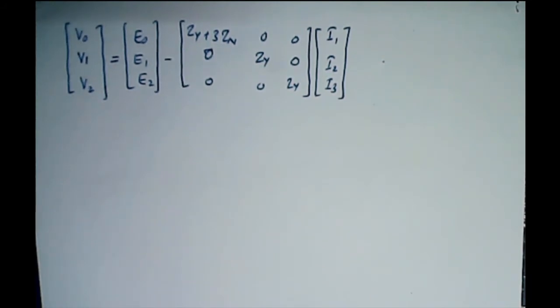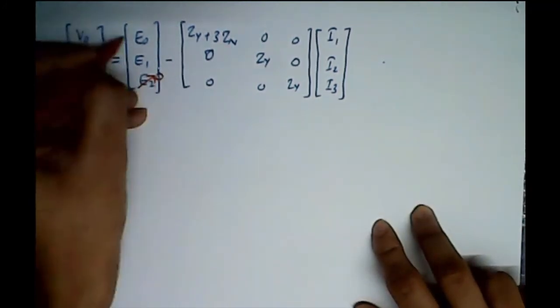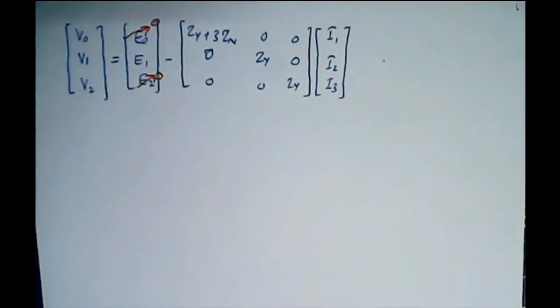This means if the magnitude of a generator rated at 11 kV gets low, then all the phases will have a magnitude of 7 or 8 kV. Now this means that the internally generated voltage in a generator is always balanced, and when it is always balanced, this means what? The negative as well as zero sequence components will be zero, right?